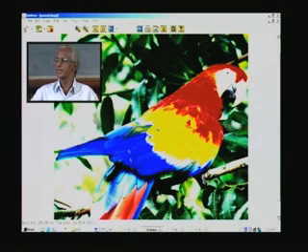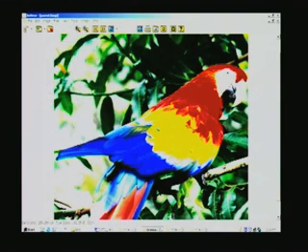You can see that the picture is not that good. You can see some information being lost. This is because it is 256 by 256, although it continues to be true color here. If you zoom both these pictures, for example the first high resolution picture, you will get all squares, and each of these squares is known as a pixel, and a collection of 64 pixels, that is 8 by 8 pixels, we take in order to process a DCTQ.